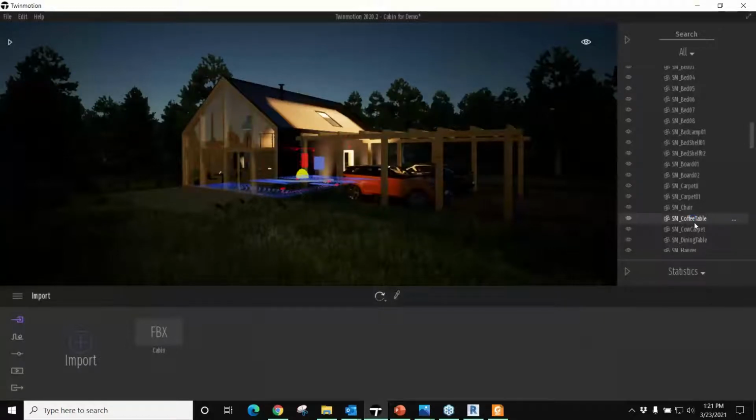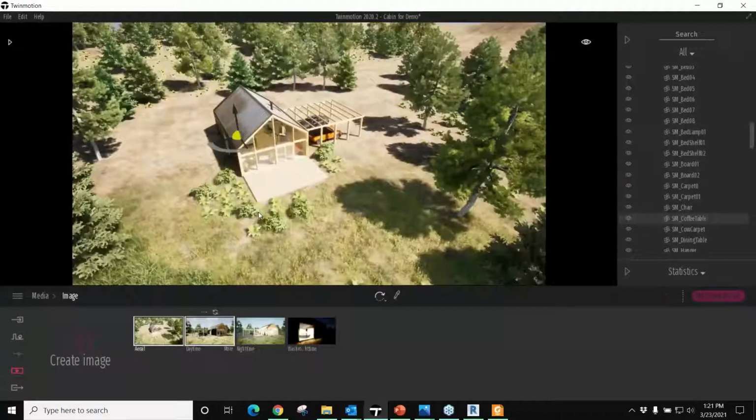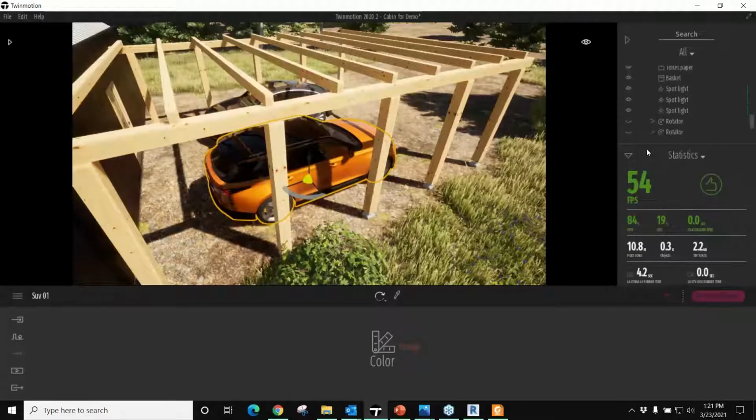But when you click on an object, I just hit the shortcut key F to get to it, and it takes me right to that object. Let me see, why am I still in there? There we go. So you can do this too by clicking an object and typing F. It basically does a zoom extents around that object. So those are the 2 main parts of the interface.